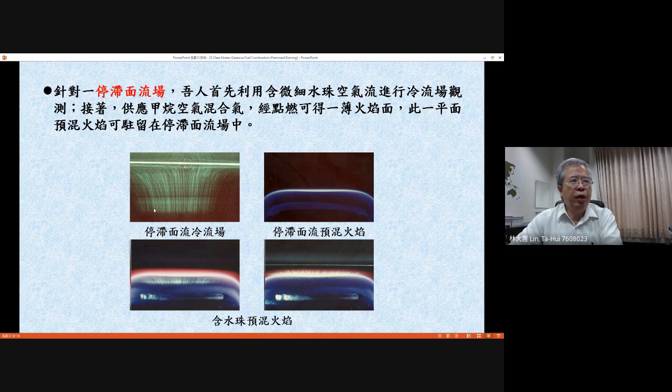In this region, the flow structure can be described very well by the so-called opposed flow solution, which means if you take a cross section in the flow, that means you fix the axial coordinate along this cross section, and you do the measurement of axial velocity, you will find they are uniformly distributed along the radial direction, which means when you ignite it, then you will have a planar premixed flame.